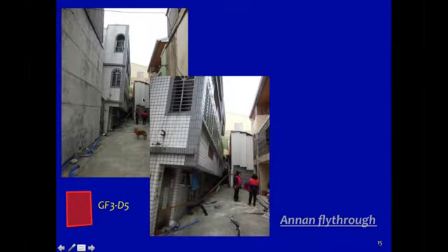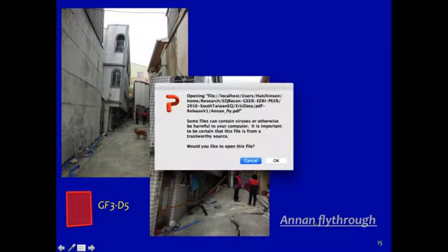The lightweight single-story rear structure, which shows significant distortion, as it must attempt to carry the large shear strains that are induced during the collapse of the building it's attached to the right. To gain a perspective of this scene, we captured a suite of LiDAR scans at this location. And here I want to try to play a movie and fly you through a sequence of this LiDAR model.